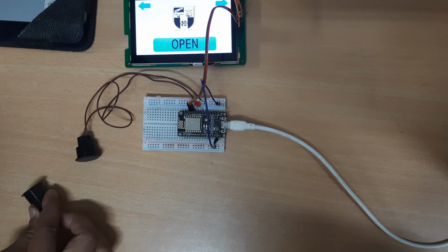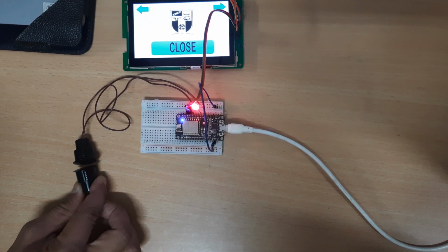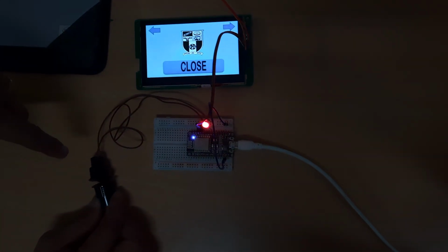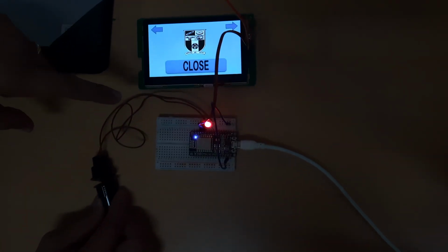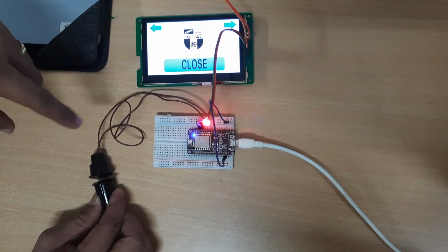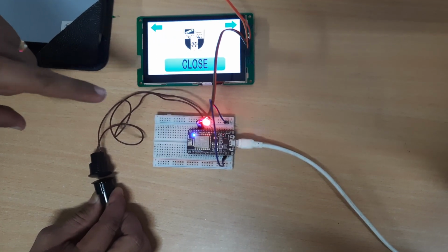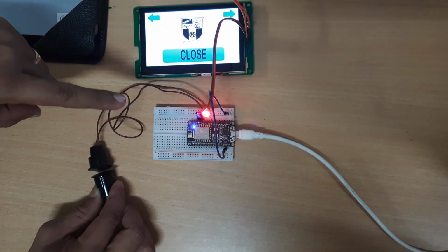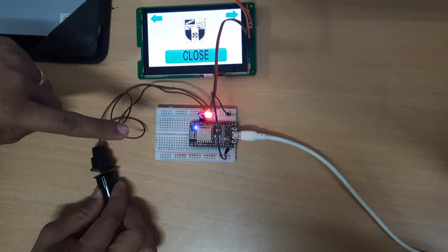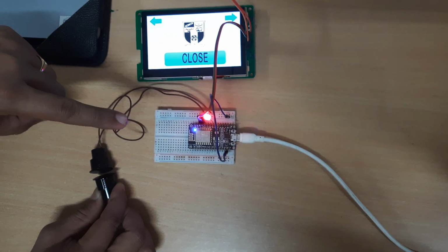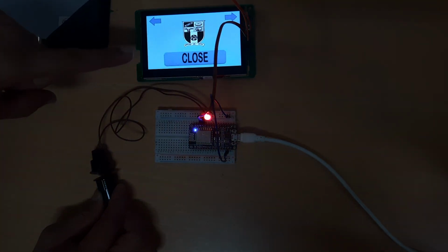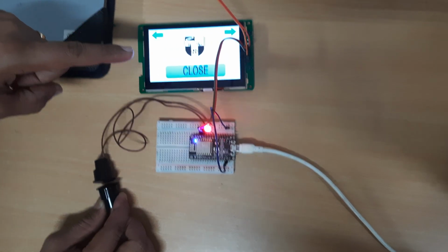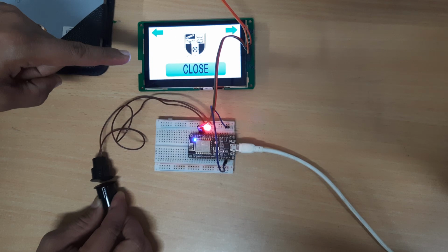So whenever the door comes closer to this reed switch, the reed switch will be on, and there will be a transition from logic 1 to logic 0 in the GPIO pin, which is notified by switching on an LED in the node MCU. This node MCU is transmitting the data through UART to the DWIN touchscreen display, and the touchscreen display receives the data and displays that the door